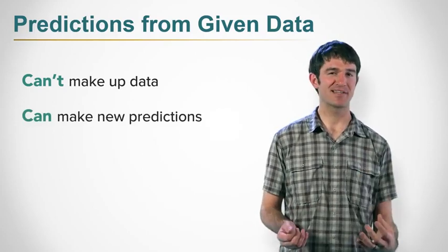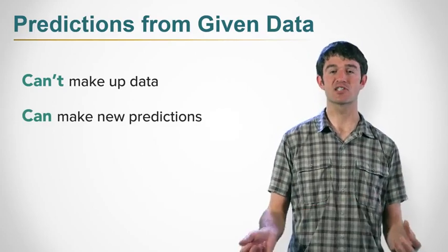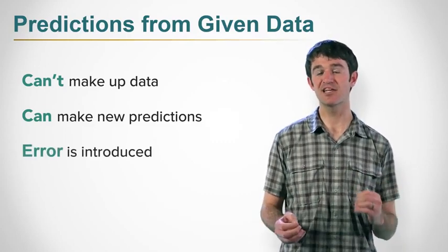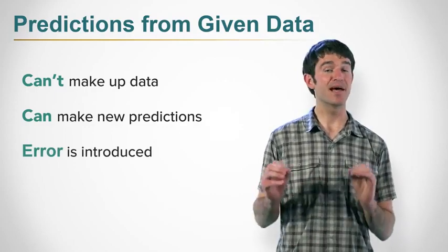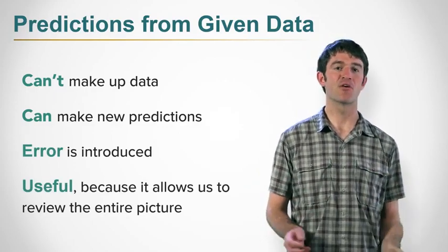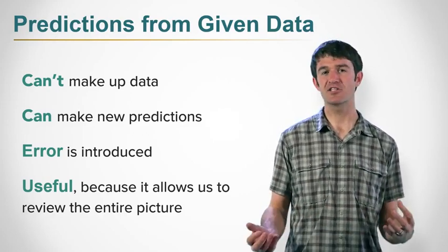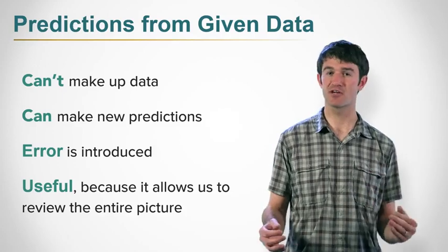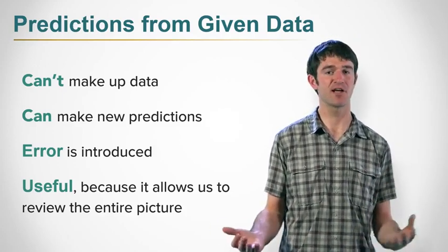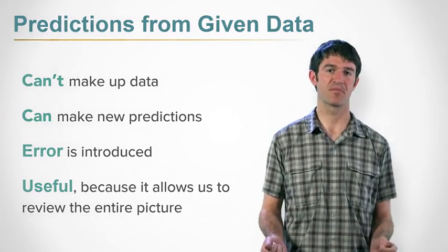That's what interpolation's good at. That may seem like semantics, but it does matter. Remember the lessons from the previous course on sources of error. This is one of those times where we're inserting a not completely known amount of error into our data. But it's still useful to do anyway because it allows us to look at the complete picture rather than just the pieces we were able to collect data on. In our elevation example, it's the difference between having a few surveyed locations and having a terrain model capable of simulating solar influx, water flow, suitability for human needs, slope, and more.